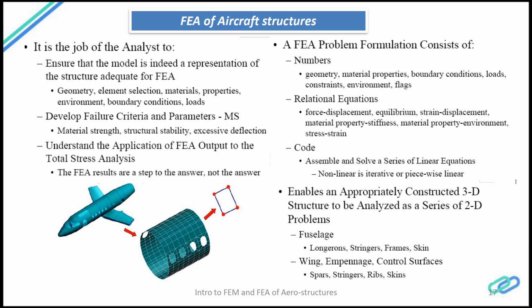And then finally you should assign the failure criteria. Suppose it is a composite model, you may be required to assign failure criteria such as Tsai-Hill or Tsai-Wu, and the parameters for the failure criteria and material strengths before you run the analysis, because different industries use different failure criteria for their materials to be qualified. And again, the steps, what kind of steps you should take in order to achieve the result.